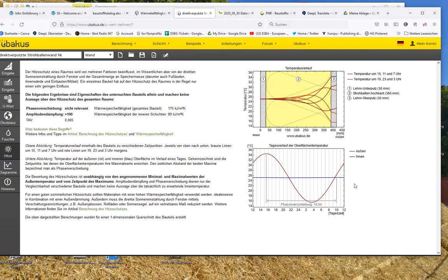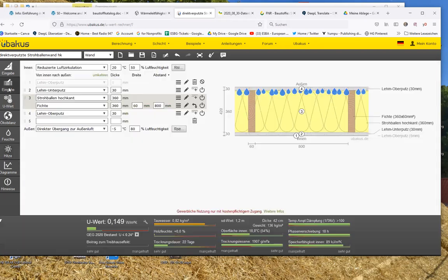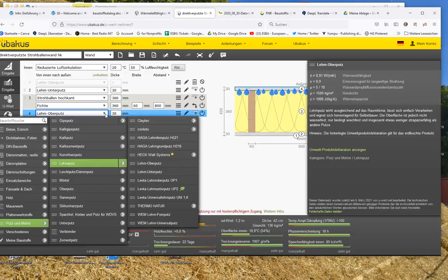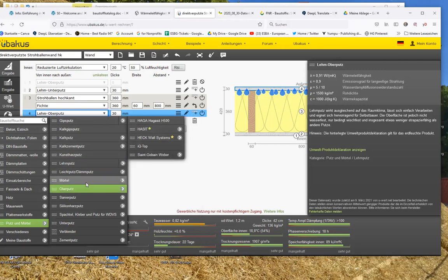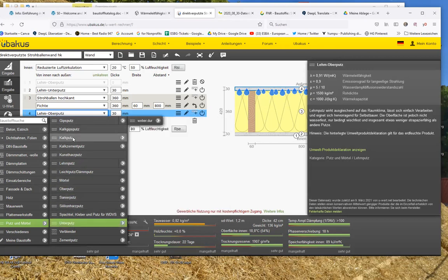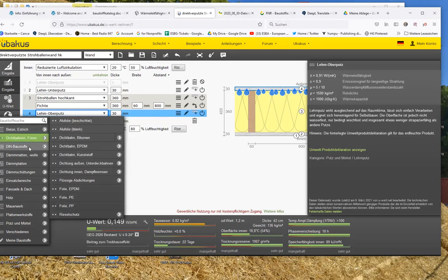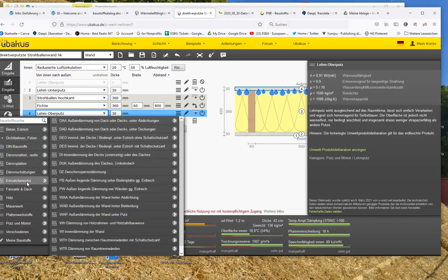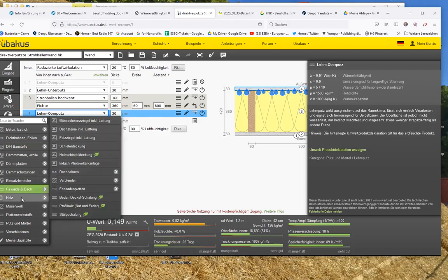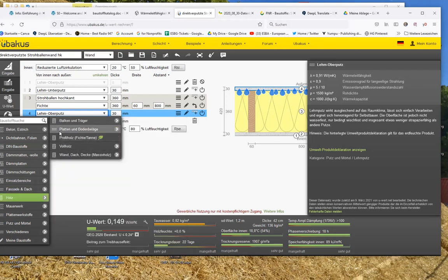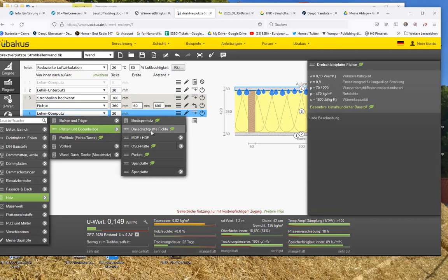But if you have this wall which is not from straw bale, but maybe just OSB board and EPS and OSB board, it would be much more important. Yes, then this amplitude is much more important to design for 12 hours than 18. Maybe here, when I see it on the chart, it's almost not important in straw bale because it's already such a big capacity that the change of temperature inside is not.